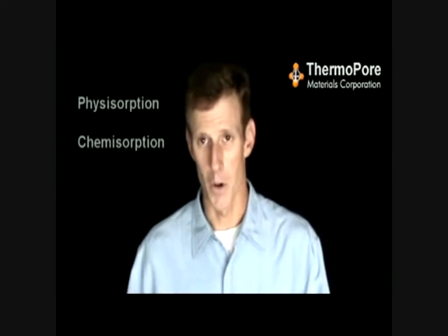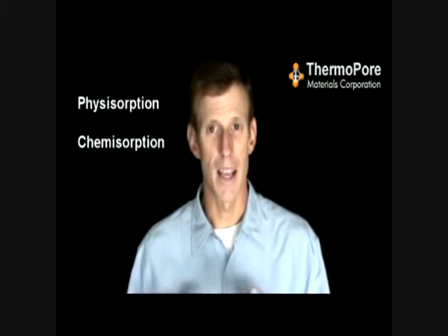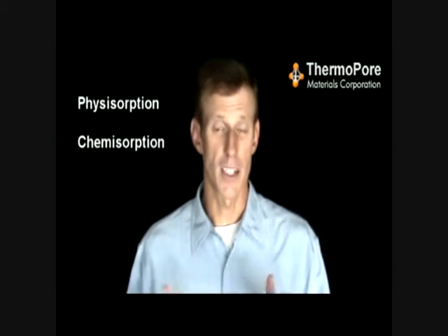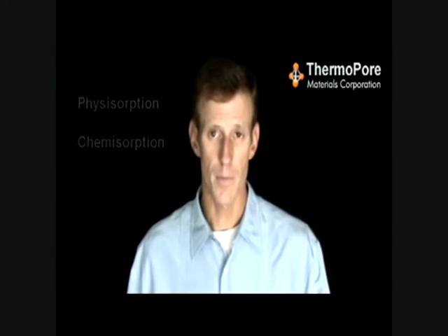Well, it turns out that there are two subclasses of adsorption: physisorption and chemisorption. These terms might sound intimidating, but hang in there. Their definition is actually rather straightforward, so our discussion will quickly come into focus. Physisorption relies on an attractive force between the adsorbent, in our case a filter component or an additive, and the adsorbate, those particles or molecules that we're looking to capture or filter. Once in contact with one another, the adsorbates remain in contact with the adsorbent due to van der Waals forces.